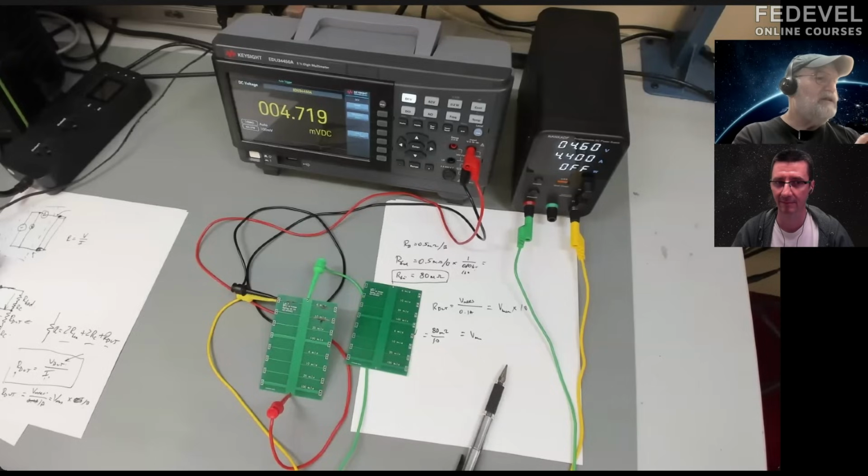It's perfectly fine, a 20 mil wide line. That's half a millimeter. Yeah, exactly, a half millimeter wide line. And for signals, rarely are you going to get an amp of current through signal lines. That's why a 6 mil wide line is perfectly reasonable for signal lines.